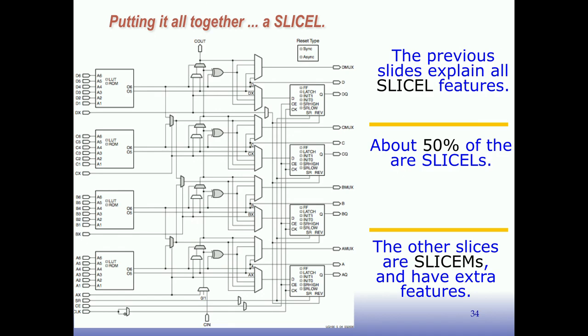And this was a tricky idea that came up probably 15 years ago now. If you think about these LUTs, which are here, the blocks shown here, these are the flip-flops, these are the LUTs. The LUTs have a lot of these latches in there. Okay, the latches are typically set by the configuration bit stream, which defines the function of the logic blocks. Well, those latches look like little memory cells. Right? So if you add extra logic, the circuit out here could read and write those LUTs and treat those LUTs as like little memories. Right? And that's what a slice M does, is to use those latches so that the user circuit can read and write those latches, not just the configuration bit stream.